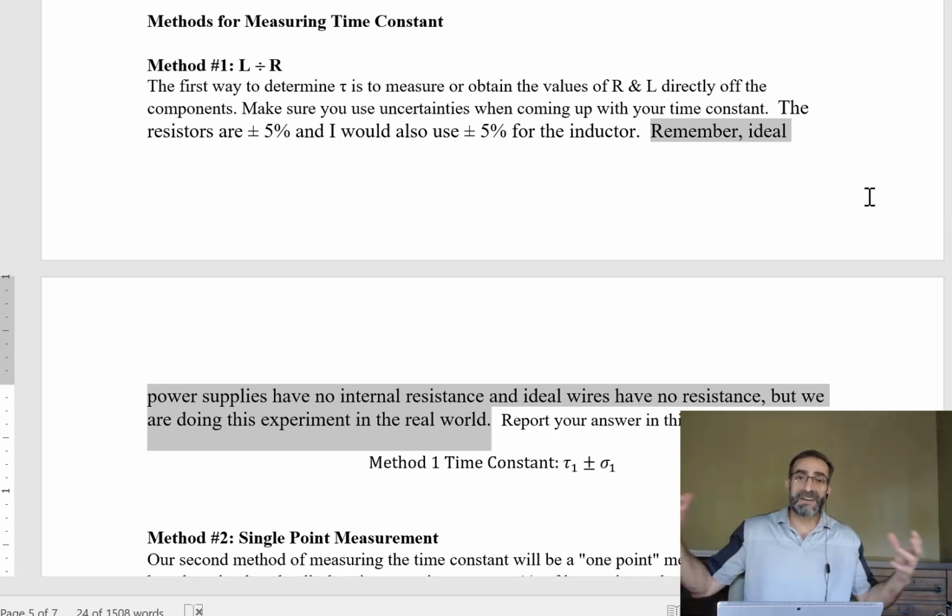But this is a ton of wire, a lot of wire wrapped around and around to make a nice coil. And there's so much wire there, we can actually measure the resistance of that. It's somewhere in the 5 to 6 ohm range. So 5 or 6 ohms, it's not a lot, but the resistance that we're using is only 100 ohms. So if we ignore it, we're introducing 5 or 6% error in our results right off the bat.